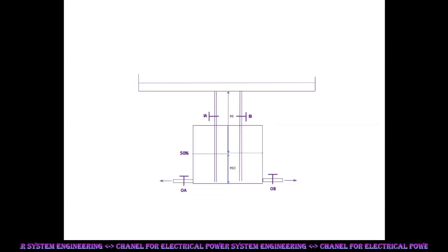Outflow head ho is decreasing with dropping level. This head ho is also common for both the outflow lines. Hence outflow from both lines OA and OB is decreasing. This will continue till total inflow matches total outflow. Thereafter water level in the tank is steady. In this setup the mismatch of flows, which occurred due to increase of outflow from OA, is automatically adjusted due to increasing inflow of two lines and decreasing outflow of two lines. Therefore flow matching is quick with less level drop. In case of more inflows and more outflows the level drop may be still smaller.